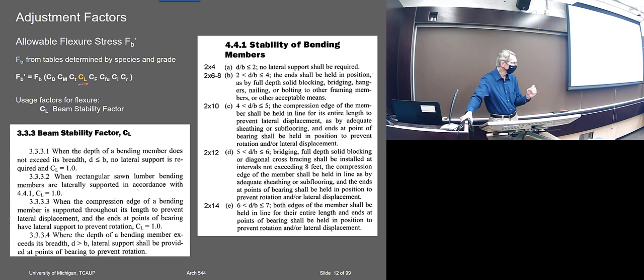The idea is, when I load it, if it has lateral torsional buckling, this is what accounts for that lack of stability. So I load the beam and it flips out sideways. And a thin joist could very easily do that. It has a profile. It's only 1.5 inches by maybe 10 inches deep. If you loaded it, it could easily flip out sideways.